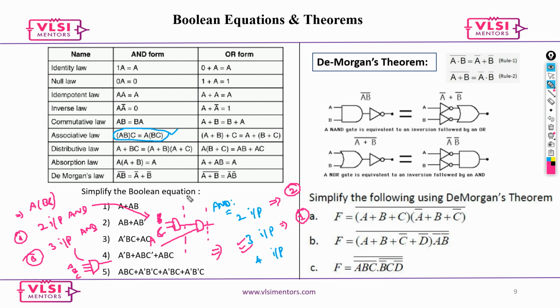If your block needs to operate at 2 gigahertz, like a CPU, performance matters. Power is second priority, but it is also as good as high priority. To answer that, we always target frequency, because without hitting the frequency, you won't tape out. First of all, you cannot sell the chip to a customer.